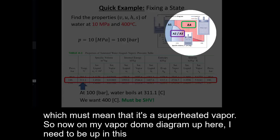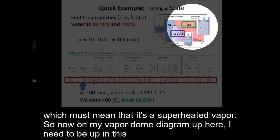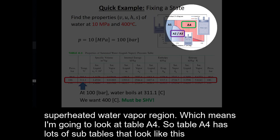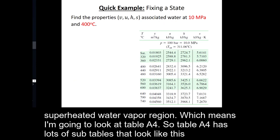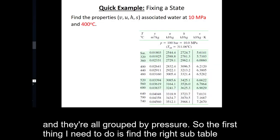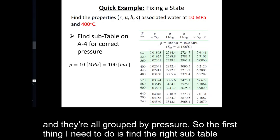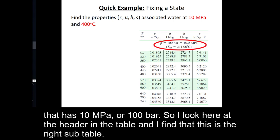So now, on my vapor dome diagram up here, I need to be up in this superheated water vapor region, which means I'm going to look at table A4. So table A4 has lots of subtables that look like this, and they're all grouped by pressure. So the first thing I need to do is find the right subtable that has 10 megapascals or 100 bar. So I look here at the header in the table, and I find that this is the right subtable.